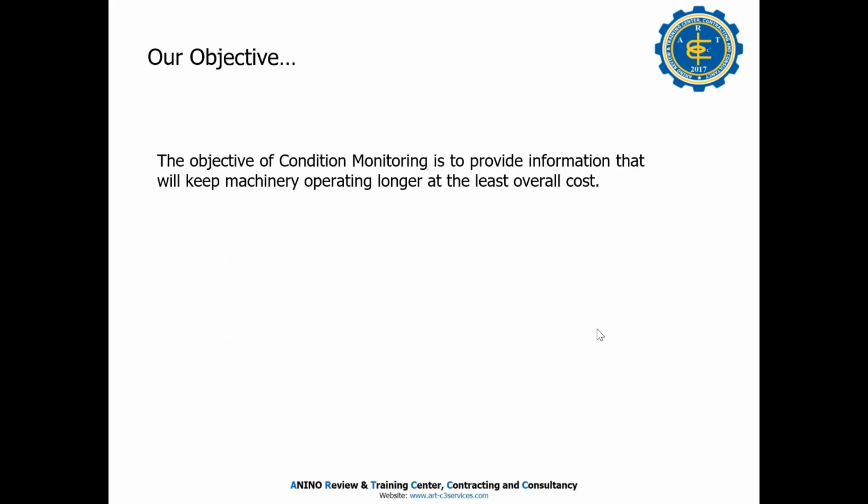So that's the target of reliability. In maintenance, if they encounter a problem, they will always say stop the machine or shut down the machine. But in reliability, no. That's why we have vibration monitoring, offline and online. Reliability can say that we cannot shut down, but we have to monitor.